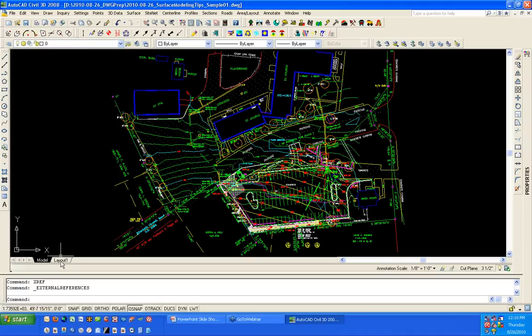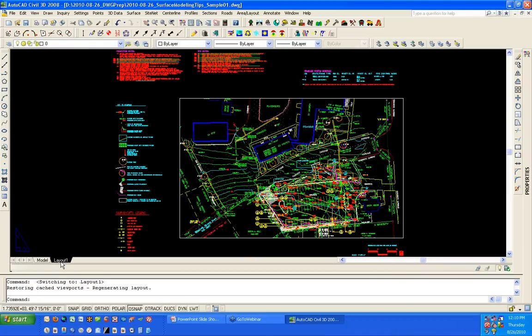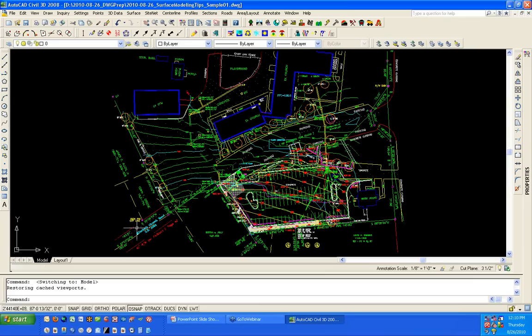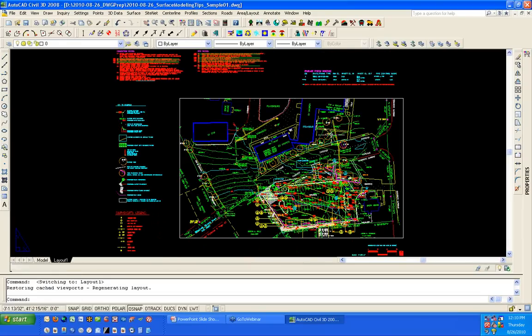And then the second thing is, how is model space and paper space being used? Well, we have entities in both. I would say in at least 50% of the cases, all of your project information will be here in the model tab, but every once in a while we'll find some actual entities that are important to us, information that's important to us in the paper space.